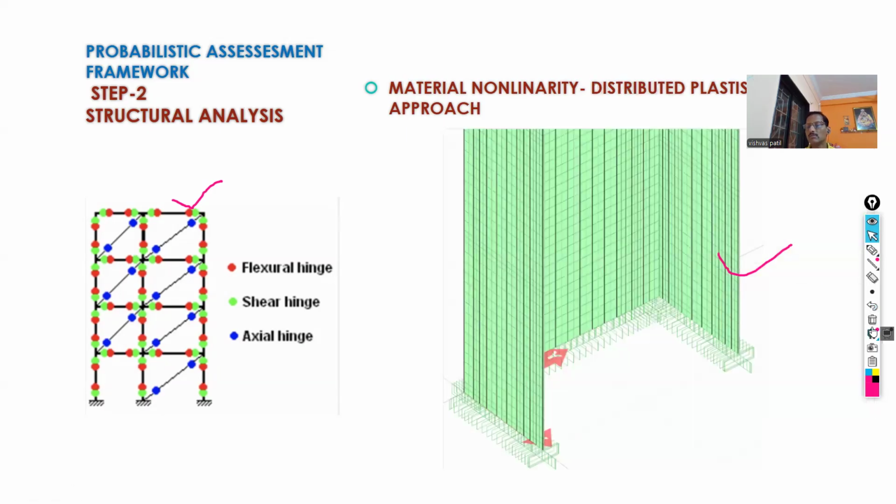Now the shear wall is an area element or shell element to which nonlinearity can be applied in both ways. Either we apply it by the lumped plasticity approach or by the distributed plasticity approach. That means the nonlinearity is assigned for a complete area. In SAP 2000, there is a command called multi-layer shell element. By using that command, we can assign the nonlinearity to the shear wall.